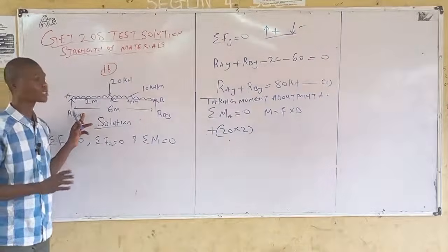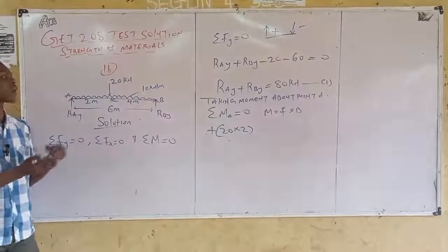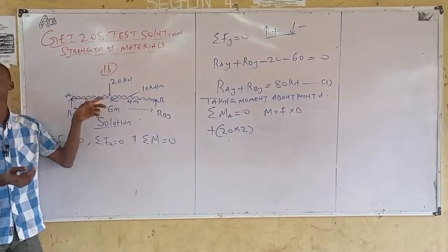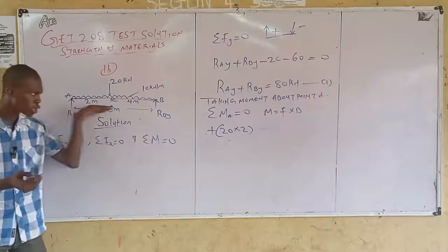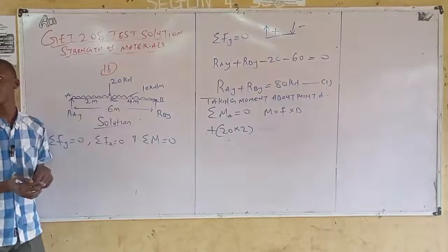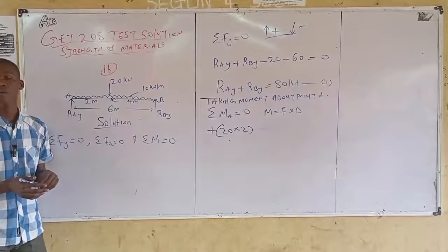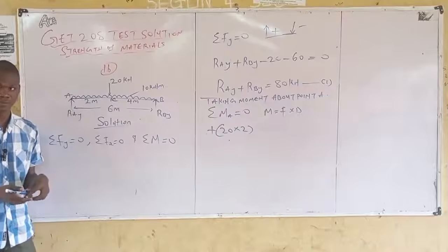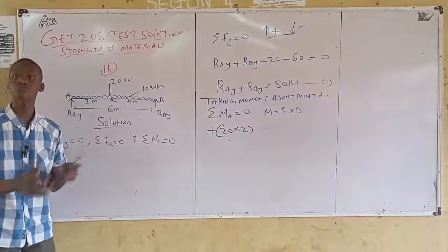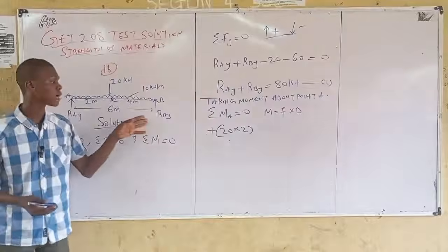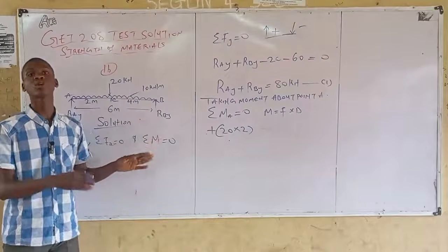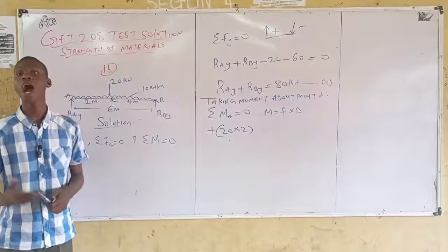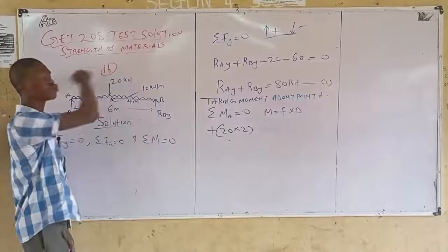2. Right? Moving on. You know, I said I'm going gradually. When I got to C, I saw this point load here. That's why I considered it first. Right? Going on now. What's the next force I'm seeing? Which one? I'm seeing U.D.L, right? And what? RBY. So let's take it one by one. I'm seeing a U.D.L and I'm seeing RBY. Okay, which one should we go with first? Is it the U.D.L or RBY? RBY. Meaning RBY is traveling towards point A.